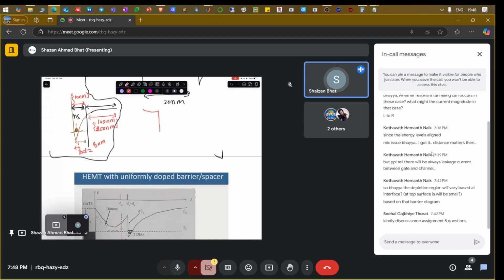I was working on a device that was AlGaN and GaN and had a sheet charge density of some value. This centroid is 2 to 3 nanometers away from the interface, and the GaN was modulation doped on this side, so that this particular layer was intrinsic GaN. This particular layer was C-doped GaN, and there were other layers, leave it.